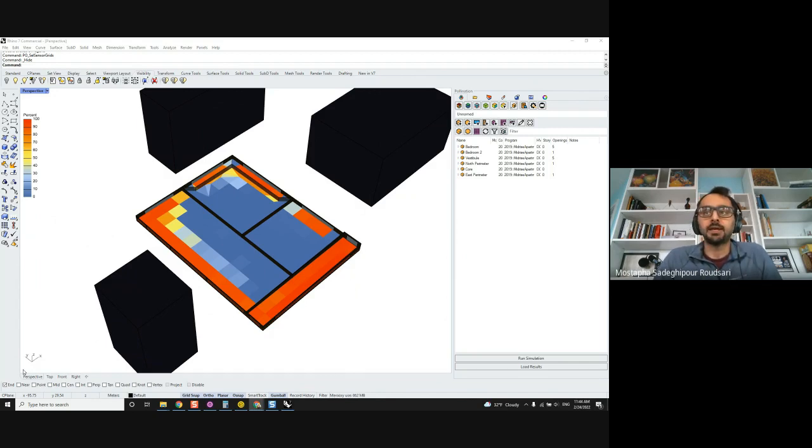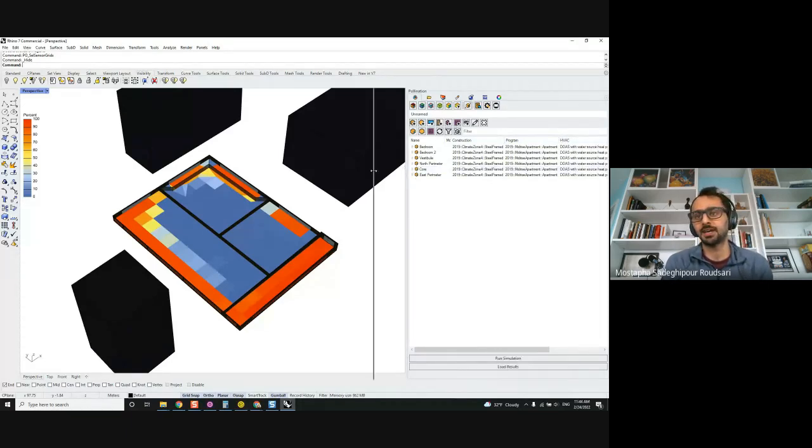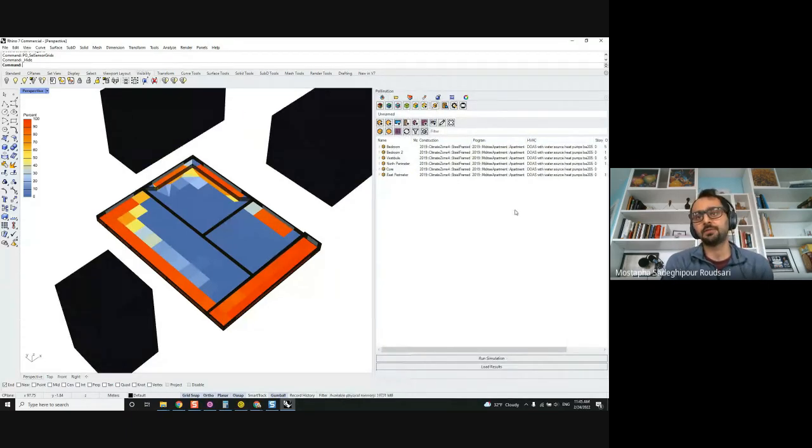So it depends on the type of simulation. For energy simulation itself, we can use better machines, and we are using 64 bits, but we cannot run EnergyPlus in parallel. There is a project going on, EnergyPlus 10x faster, which will provide some multiprocessing functionalities for larger buildings. As soon as they support it, we can support it too.